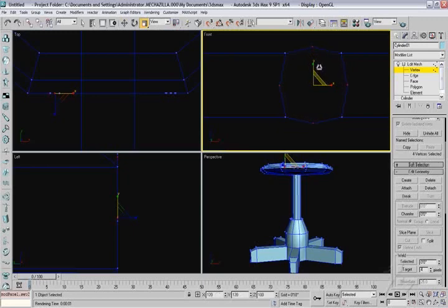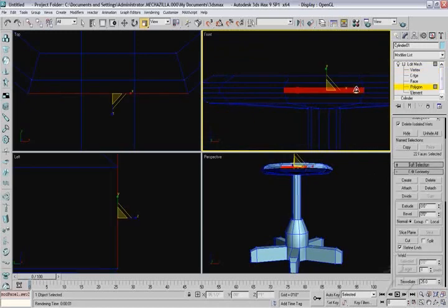Just scale that out so that I create an octagonal polygon. Okay, now that I've got that, I'm going to zoom out using my front viewport, and you can see those two polygons we've created. Now we'll go back to polygon mode, and it has our original selection here, so we can hold down Alt and click right in the middle, and it will deselect the outer one, and then you can deselect those also. So basically all we're after, you can just single click and use Control to grab them.